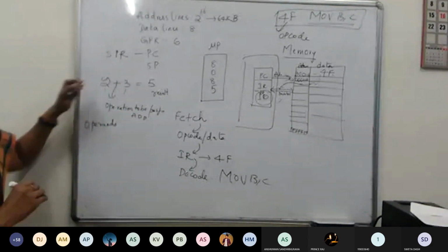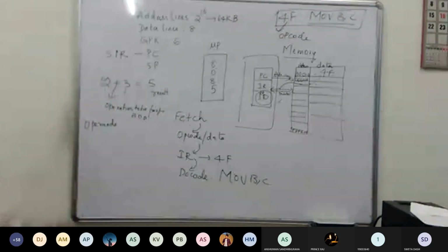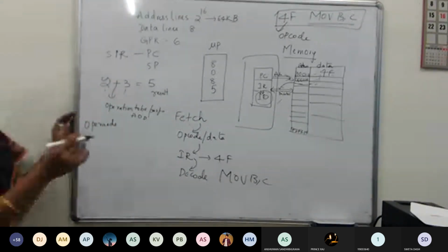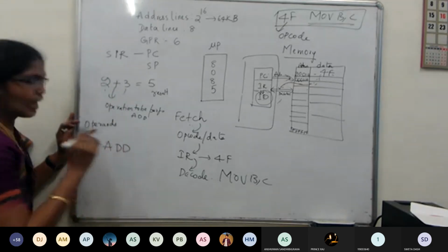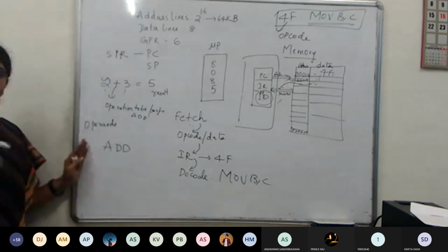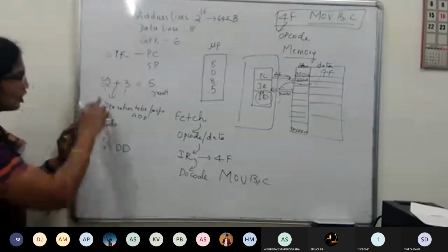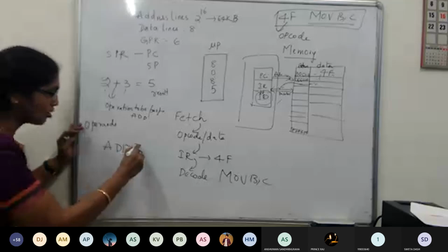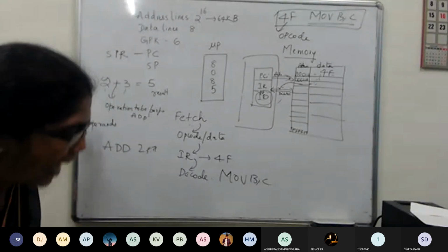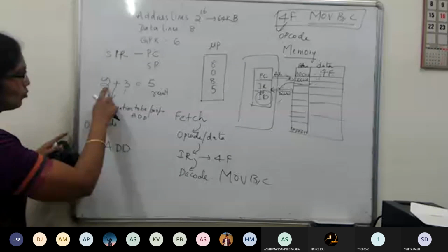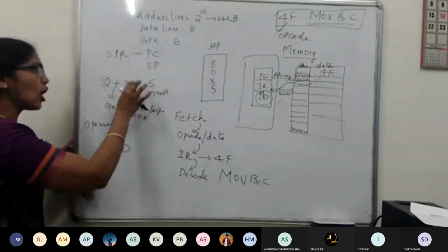Now, if at all I want to do this work in the microprocessor in general, normally I have to use assembly language coding. So ADD stands for addition. This is already add, meaning it will understand. But hold on. Now, add 2 plus 3. I cannot write 2 comma 3. I have to store 2 in one register and 3 in another register, then do the operation.